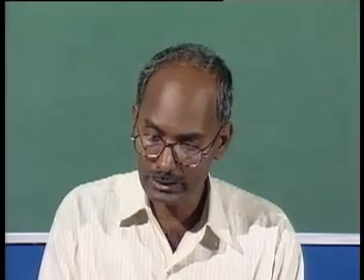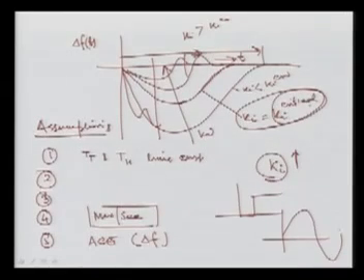So for measuring the frequency, at every point that we are measuring, we then calculate the frequency. It was assumed to be continuous, but in reality the measurement of the frequency deviation, that is the change in delta f here, takes place discontinuously, in a sampled-data fashion.